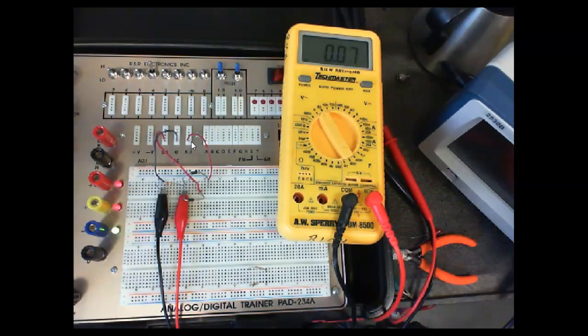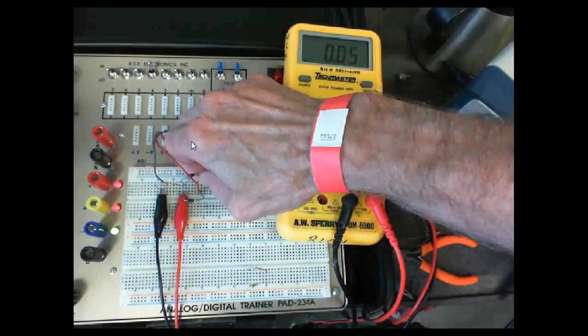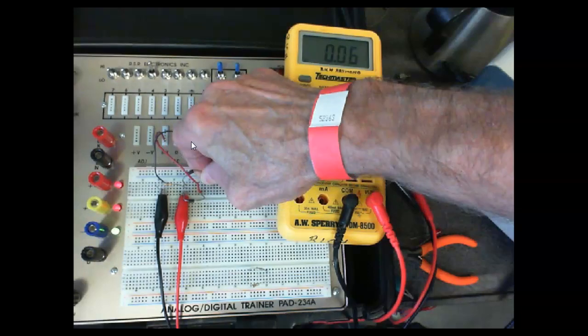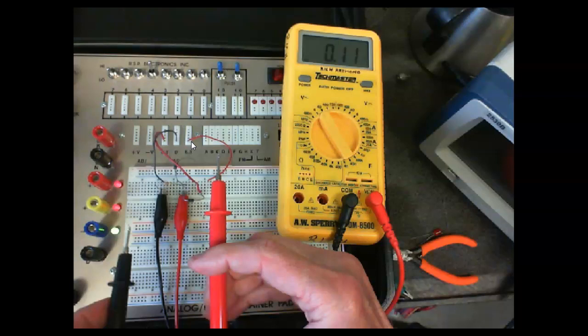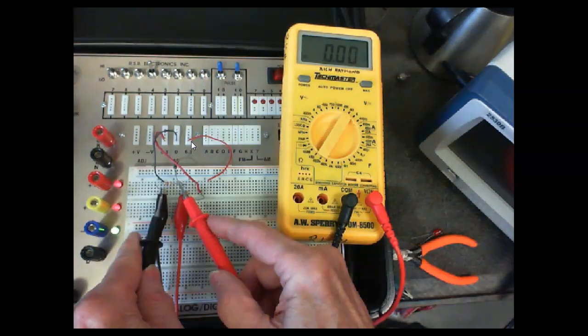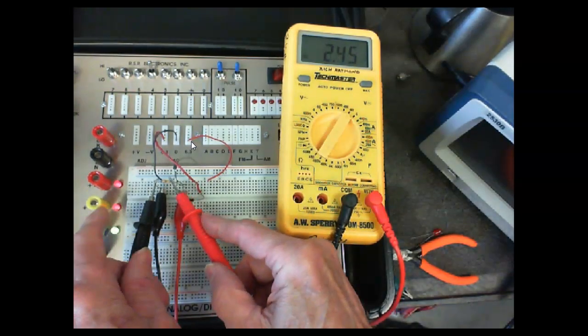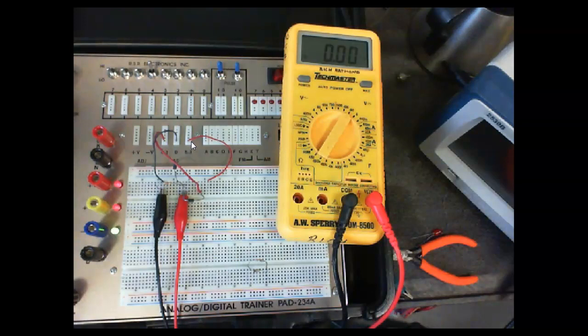So if I open up one of my diodes, and I'm expecting 5.6 volts out, I come up here and measure across it now. Let me put it back on DC. I measure across it now, and we notice there's your 2 point something volts. So right off the bat, I know it's measuring 1/2 of what I'm anticipating, which means I know something's wrong. And of course here, since we talked about it, I know one of my diodes is open.